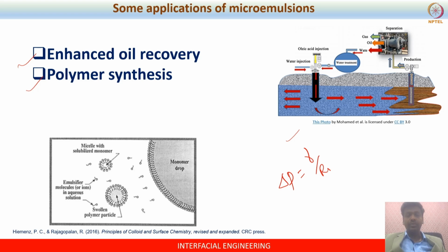psi. So it is very difficult to visualize any flow condition across a pressure drop of 300 to 500 psi, because the capillary force will be very dominant due to the very high surface tension value. Typically, the surface tension will be 10 to 50 millinewton per meter.